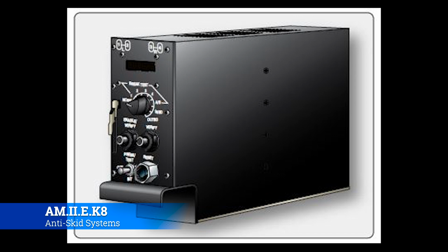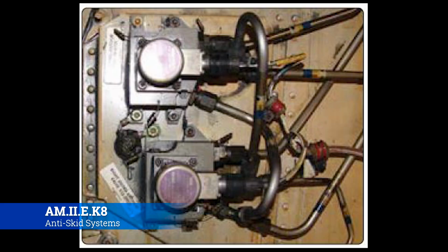So it's nested into the wheel speed sensors, as well as the electronic controls for the hydraulic system, so that it can command certain valves when need be. Okay, so this is an anti-skid control valve. Essentially, it does exactly what its name says. Whenever the anti-skid control unit says, "Hey, look, we have a skid coming up. We need to do something," these are the valves that relieve the pressure or close whenever the situation has abated, and allow the anti-skid system to work.